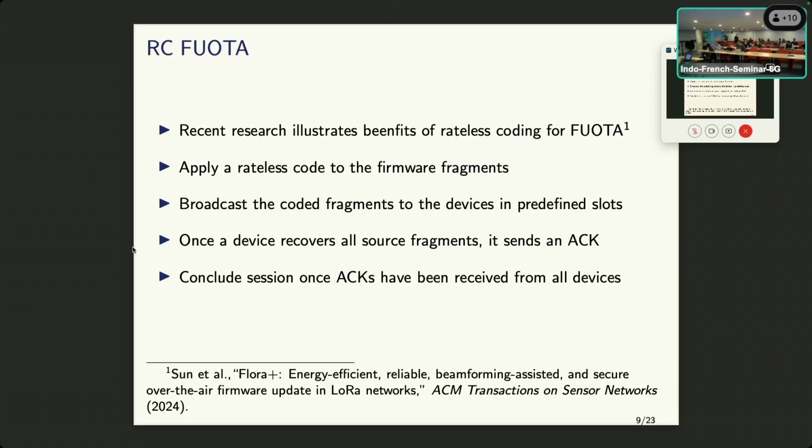But the other possibility is to use a rateless code. So we take the firmware fragments and broadcast coded fragments just using that procedure of random linear combination. Same procedure. Then the devices continue collecting the fragments. Once they are able to decode the code, they're going to send an ACK. Once the gateway has received acknowledgement from all devices, it will stop transmitting.